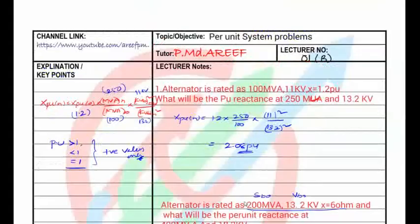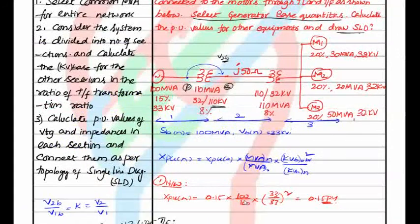Next we calculate for transmission lines. In the transmission line here, it is represented in ohms. So we would like to find the per unit values of this transmission line. The formula that we will use here is X per unit is equal to X actual value in ohms divided into MVA base divided by kV base whole square. What is the base value here? It is nothing but what we just found, 113.43 is the base voltage, and the MVA base of the transmission system is 100 MVA. So these are the base values for this system.